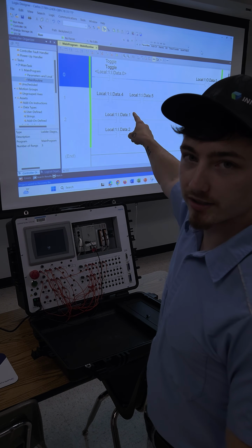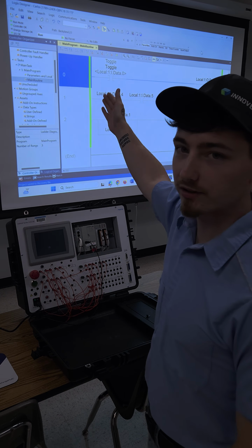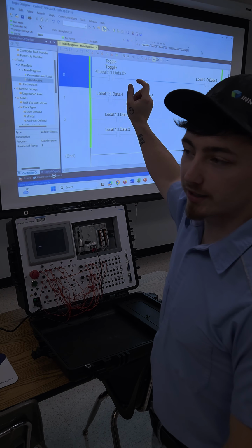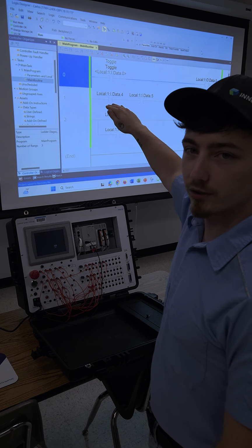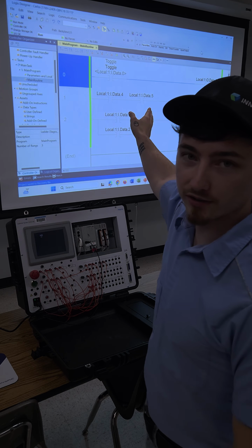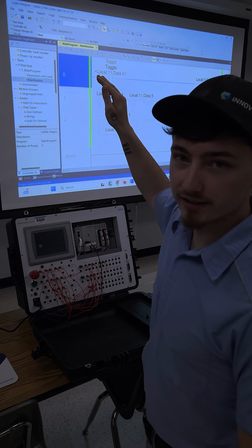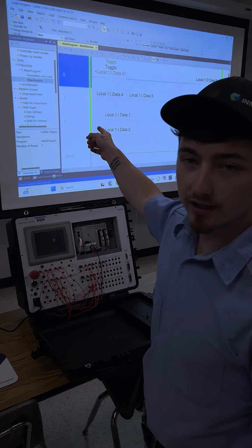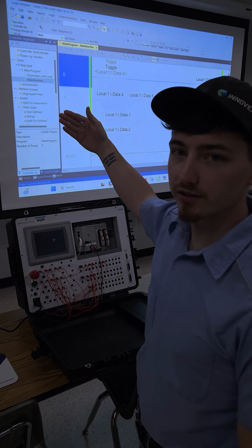And so it goes across and sees if there's power on this rail, where the 0 is. And then if it does, it's going to make that closed, and power will flow through that rung to get to the coil, which is on the very right side. And it does the same thing if you go to the next rung and the one after that. These are all XIC contacts, so they're going to do the same thing.